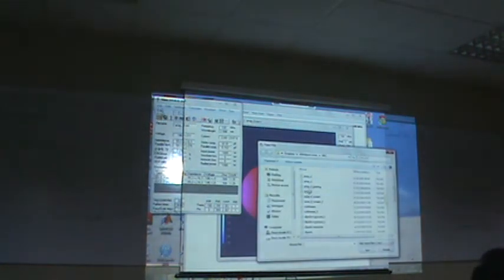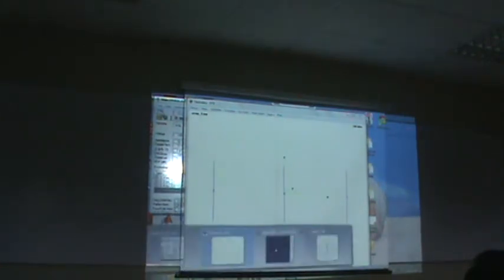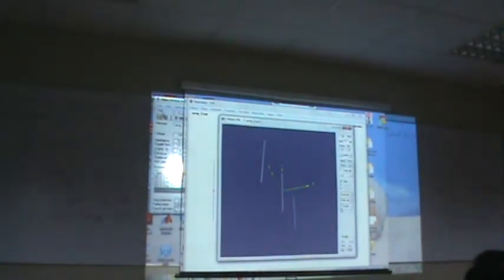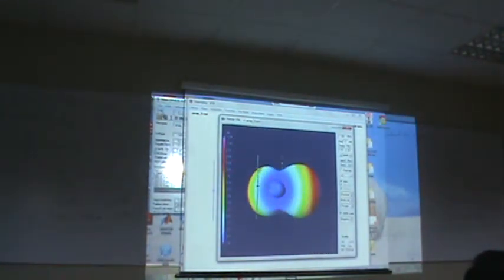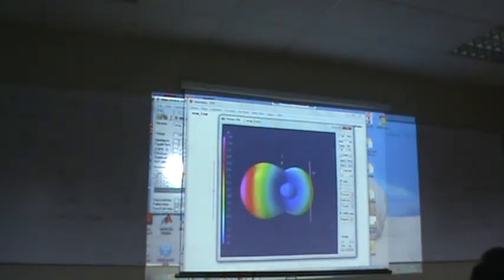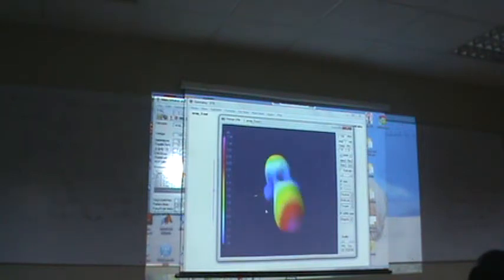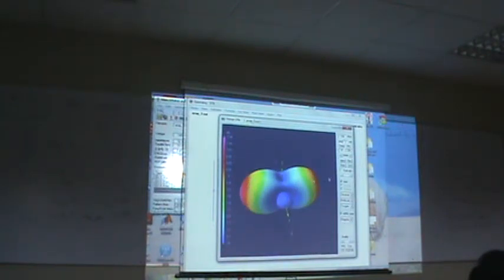You keep on building and you put more antennas on the scene, so you build more complex systems. Those are 3 antennas, and those things concentrate even more the radiation pattern. The gain is 7 dB, and it radiates in 2 directions. They're easily visible here. This is the 3-dimensional radiation diagram. This is the 3-dimensional directivity function that we talked about.